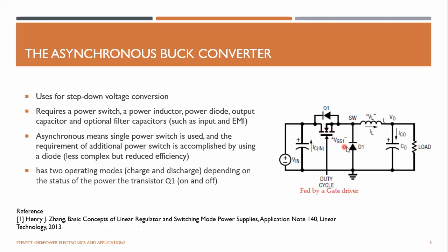But it adds more complexity. You have to switch both MOSFETs based on these square wave pulses, so that needs to handle some dead time. You can't switch them simultaneously. You have to deal with some dead time between these switches, so it will add more complexity.